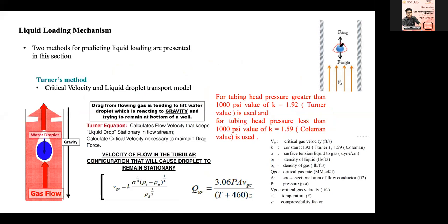In this liquid droplet, you have two forces acting in opposite directions. One is your drag force. Your drag force is basically your gas rate or gas velocity, which will try to lift your liquid droplet. The other force is gravity, which will try to push your droplet downwards.